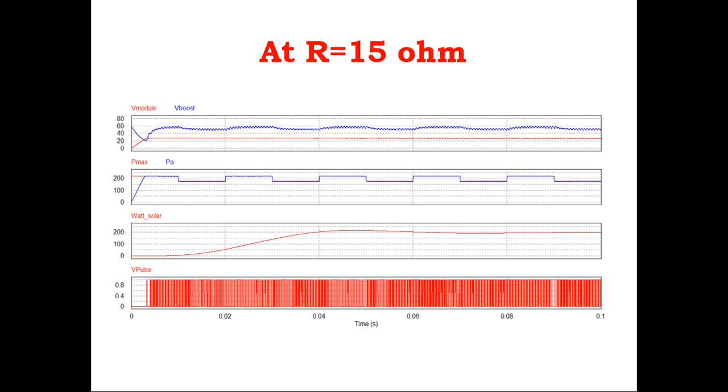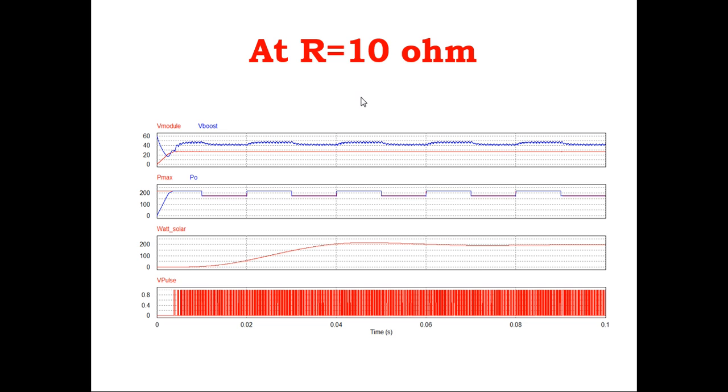In this case we are actually checking the MPPT effectiveness, not the quality of the graphs. If you increase the load current, meaning decrease the resistance, see the boosting level has decreased, but it is still tracked, and this is the power. Power is reduced in this case because the load demand increased. Afterwards, if you have a very small resistance, this PV may not feed the power according to the requirement of the load. So people prefer a rheostat to test this PV module.